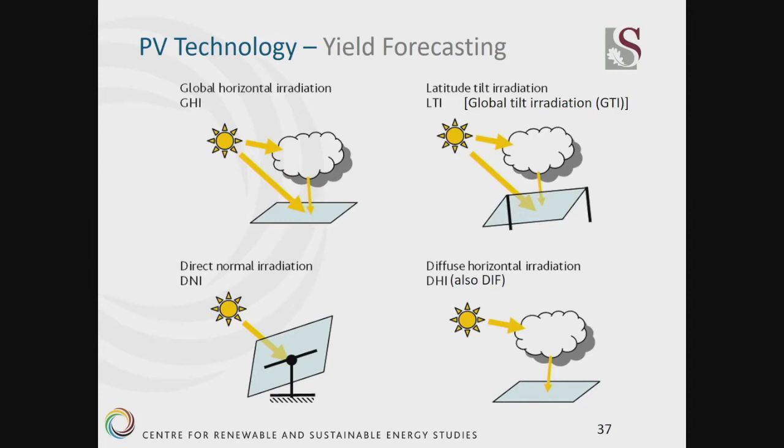Normal silicon based PV will still generate power when it is overcast. So if you did not know that, if there's any light going onto the PV, it will generate power. It might not generate full power, but it will still generate some power.